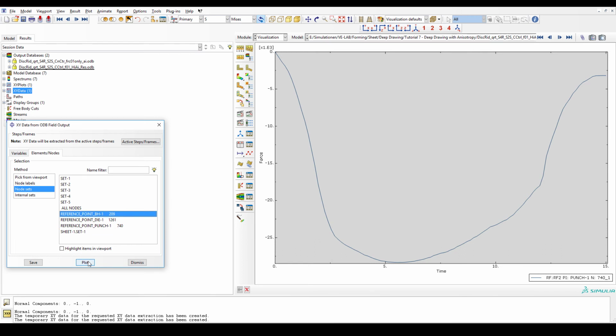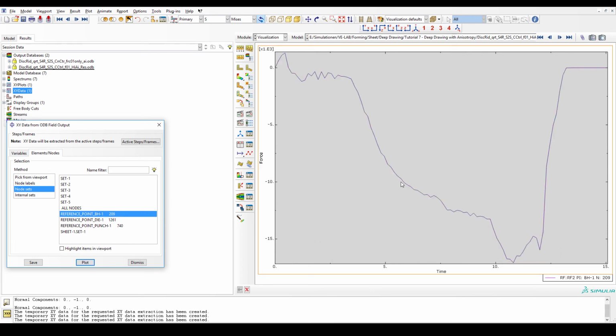Another thing I wanted to point out is the one of the blank holder, which follows a similar path. However, you have a quite abrupt drop here at the end when there is no material between the die and the blank holder. But you can also see it has an increase over time. And the thing is that if you have an actual machine, you would have to control it very specifically over time to really get to the same results.